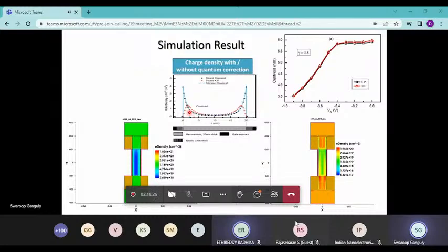What this means is effectively it would look like the oxide thickness on this side and this side has increased a little bit. And an increase in the oxide thickness will reduce the oxide capacitance and degrade the device performance. So there is a real impact of this, and that is, of course, why we are trying to calculate it in the first place. This is how the device simulation works, and this is how you have to interpret and analyze the results that you get, and that will usually translate into some impact on device performance and downstream into circuit performance.